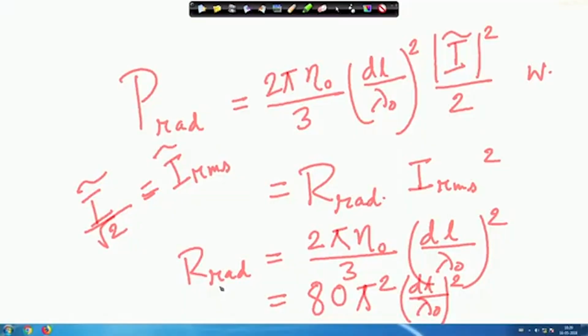In case of an antenna, power is radiated. So, radiation resistance is a fictitious resistance that dissipates the same amount of power as that radiated by the Hertzian dipole or any antenna when both carry the same value of RMS current. So, more R rad, better.